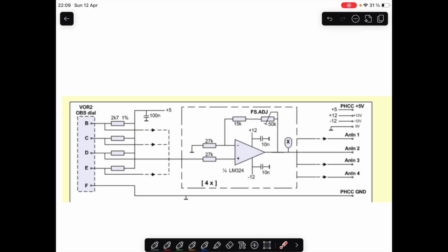And here you can see the 4 potentiometer outputs. Of course, once we have a rheostat, which is not a real potentiometer, we need another resistor to create a real voltage drop and measure the voltage here at the middle of the voltage divider.